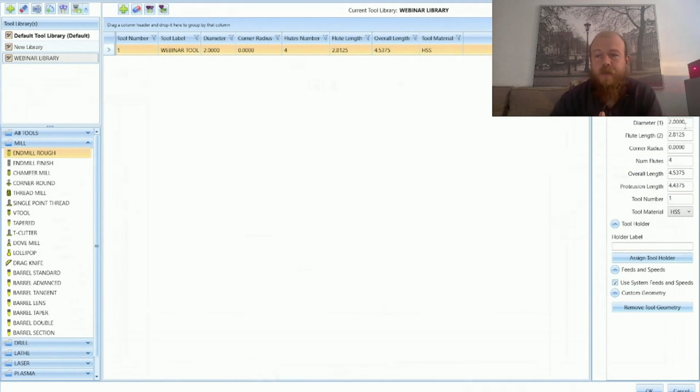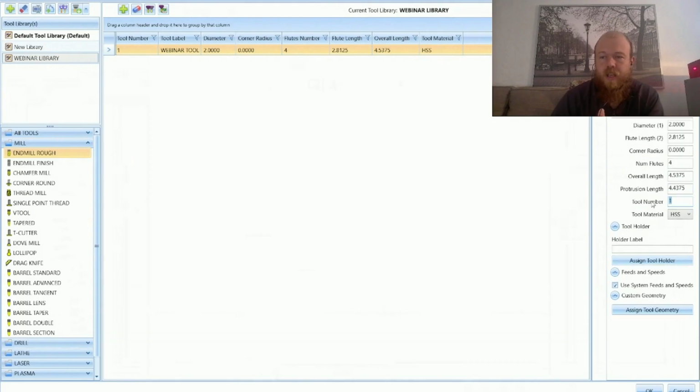You can see the diameter that it added in, the flute length, the corner radius, number of flutes. I can't really define that in a 2D shape, right? I can type in number of flutes, overall length, protrusion length, and the tool number and the...